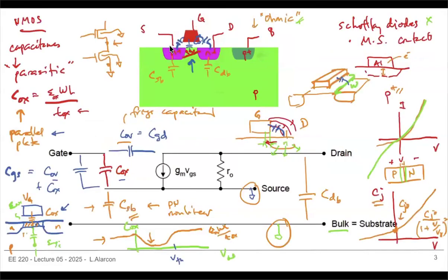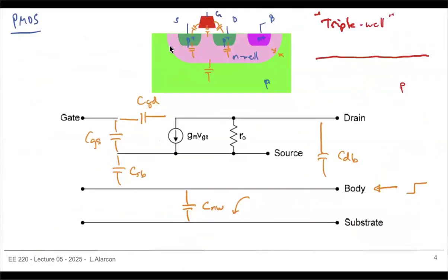Notice that for this particular setup, I can change the body bias of a PMOS, but if NMOS transistors all share the same substrate, then when I change that body bias, I change it for all NMOS transistors. For a PMOS in a well, if I have one well for every PMOS, then I can change the body bias for a particular transistor.